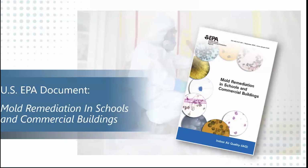So utilize the EPA document. This is a great document. It's available on the website. It's more of a pamphlet. It's like 50 pages long. And it really breaks down step-by-step instructions for handling mold remediation situations. Different types of water. Is it clean water? Are the materials affected? Are they porous? Are they resilient? Sort of gives you a guide on how to deal with remediating any mold issues.